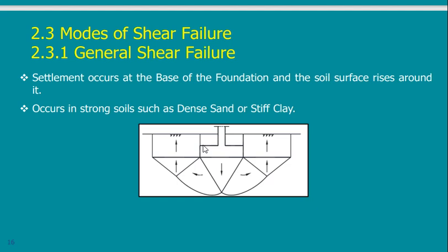You will find that around your leg there is some heave in the ground. Why is there this heave? Because of this formation. Your leg pushed the ground, and the ground was pushed laterally, and the part that was pushed laterally pushed something vertically up, and we ended up with this shape. So this is the general shear failure.